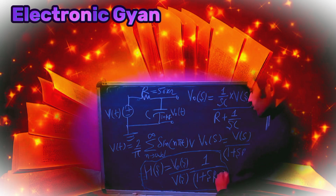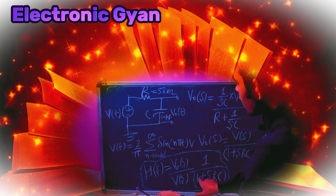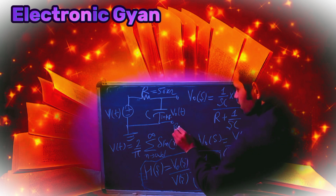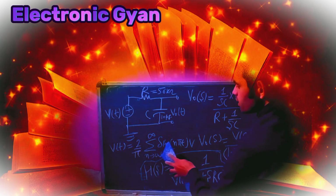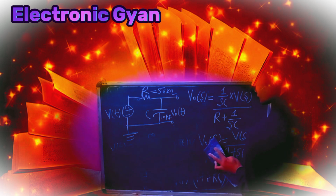Now we are going to see this in the frequency domain. This is the s domain, so we are going to find the magnitude and phase response for this. We got 1 by 1 plus sRC, where RC is, R is 50 times 10 to the power 3. So let's calculate it in the next step. Everything that we know, the input voltage is this one.